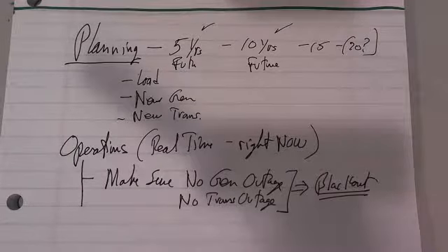And so one outage causes another, and pretty soon, if there's just not enough generation, generators go offline. The generators shut down because the frequency starts to drop. Or, if it's a bunch of transmission outages, generally that results in voltage collapse. Voltage goes down too low, and the system shuts down.